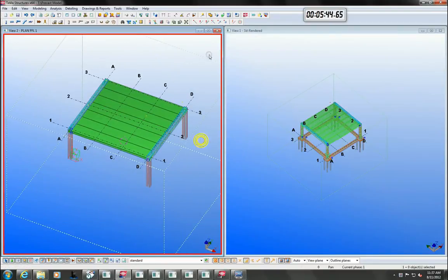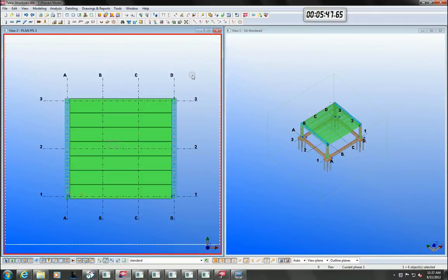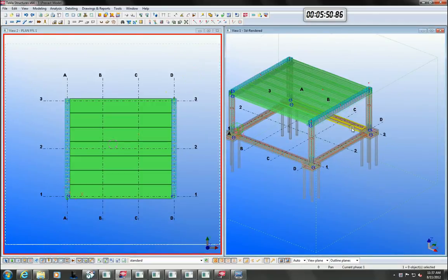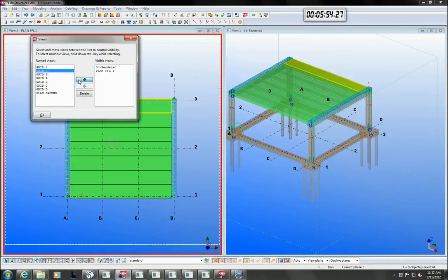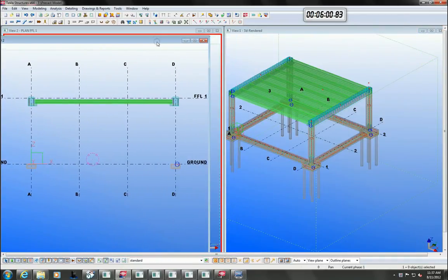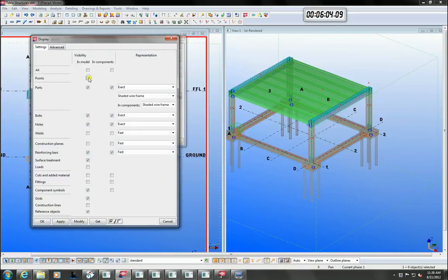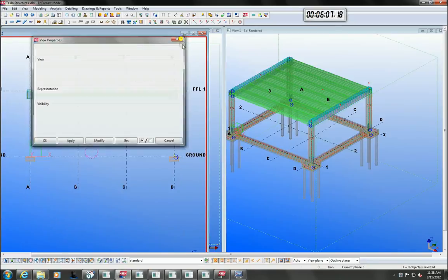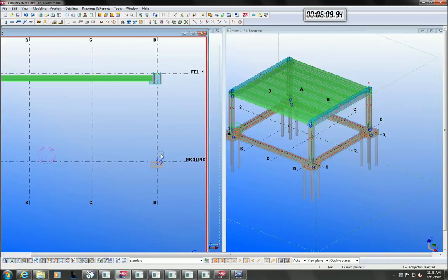Let's add some hollow core slabs between the beams and then make a set of stairs going up from the ground level through to the first floor. We can use a component to array the hollow core slabs, and then we can use a different component to cut one of the slabs and add a support to it as well. After that, we can create the stairs and bolt it down to the strip footings.